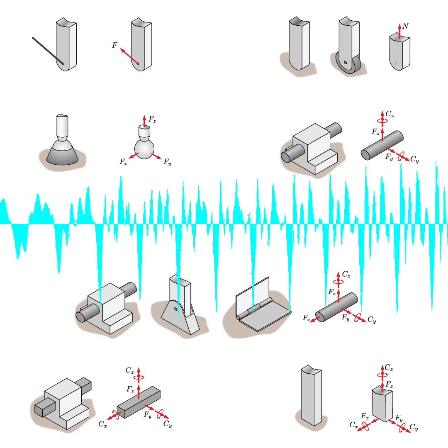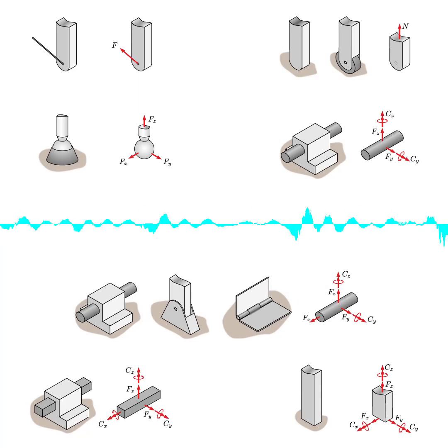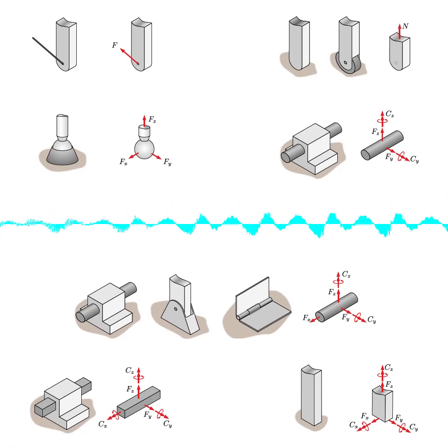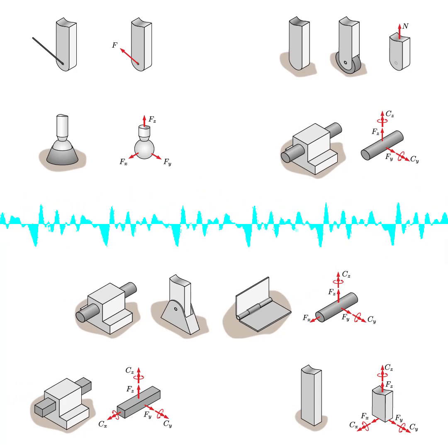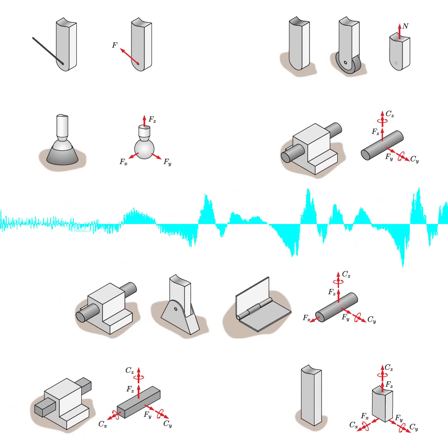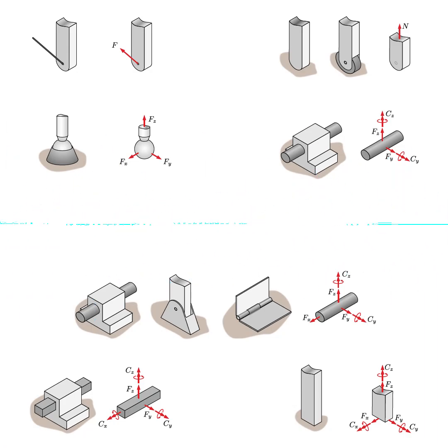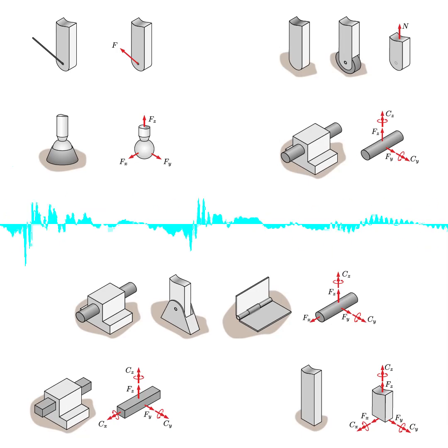0. And for the moments, we typically just have one scalar equation, which is the sum of moments about some point in that 2D plane equals 0. And then, of course, if we're in 3 dimensions, we would have 3 force equations and 3 moment equations. And the source mentions that the number of equations we need depends on those degrees of freedom that we talked about earlier. How does that connection work?